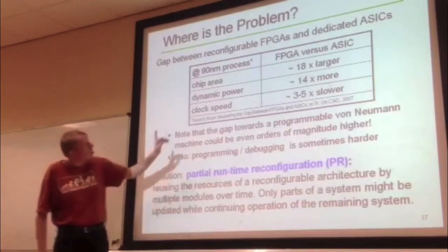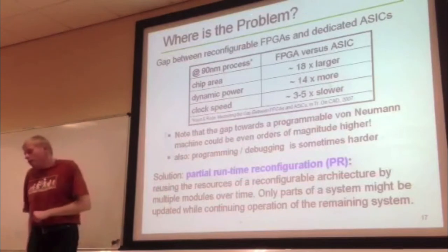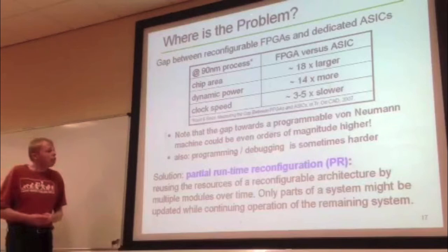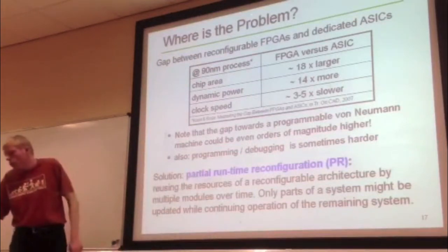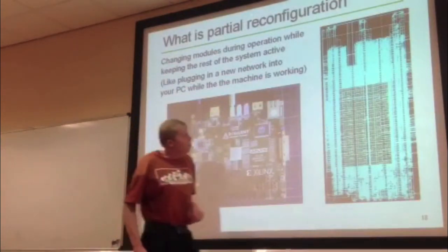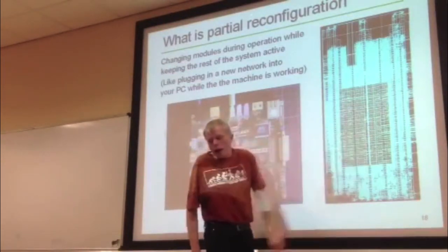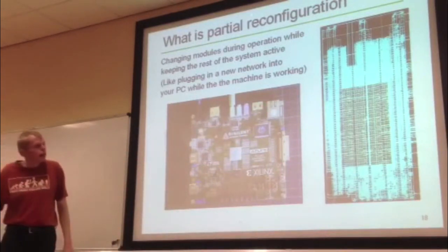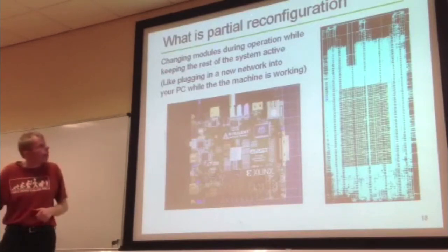Okay, and that's what I mentioned, that FPGAs allow you to have reprogrammability of the hardware at runtime. That's often called partial runtime reconfiguration. That's the stuff I work on. I don't want to go too much into detail, but the way it works is you implement your system and leave resources unused, and into this area you can place your modules later as they are needed at runtime.